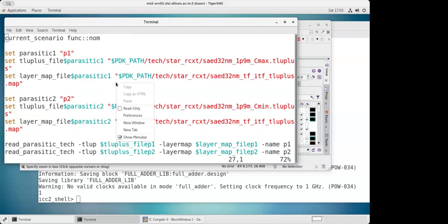In that particular wiring, metal 1, metal 2, we have discussed, remember? We also discussed that there is something like a minimum spacing, minimum width, remember? Now if you are trying to draw a wire with 2 nanometer, and the foundry is saying, okay, my mechanical machine can draw the 2 nanometer, but there is a precision.